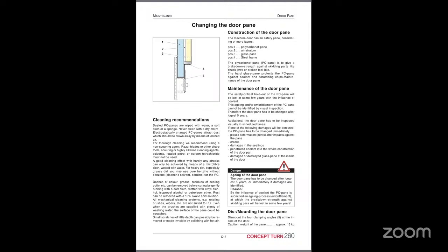If the chuck is not clamping, the problem is low air pressure. If the coolant is not flowing, that means the level of the coolant is not correct. Turret alarm, that means the tool holder is loose. Axis noise, that means lubrication issue. Poor finish represents dirty coolant. If the hose is damaged, then there will be an air leakage. If there is an issue with belt, then there will be some spindle vibration.